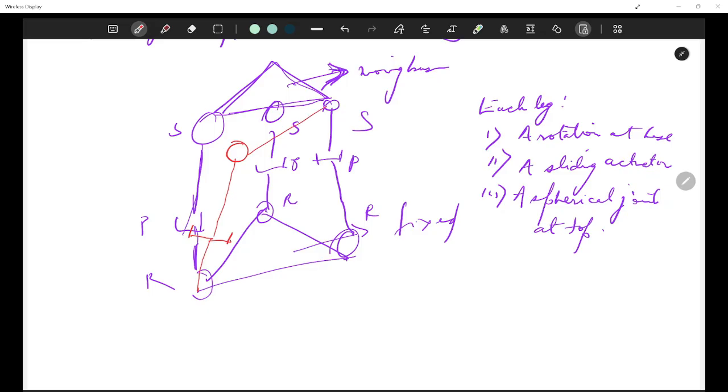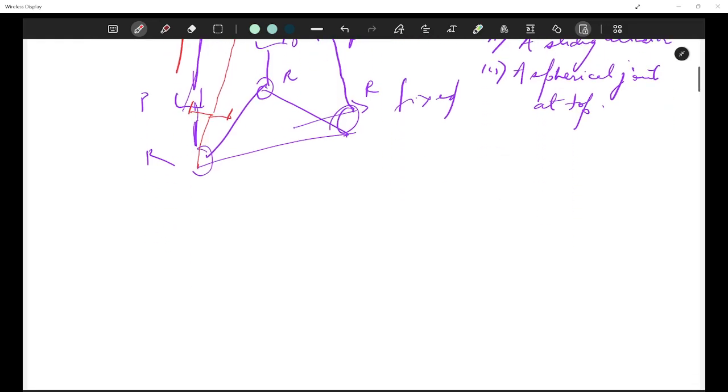So the new moving base would look like this, right? If you extend one leg, the platform tilts. If you extend all of them equally, then the platform just goes up. So by changing the leg lengths, we control mirror orientation. It is just as simple as adjusting a camera tripod. Okay, so this is an example of a very important redundant manipulator.